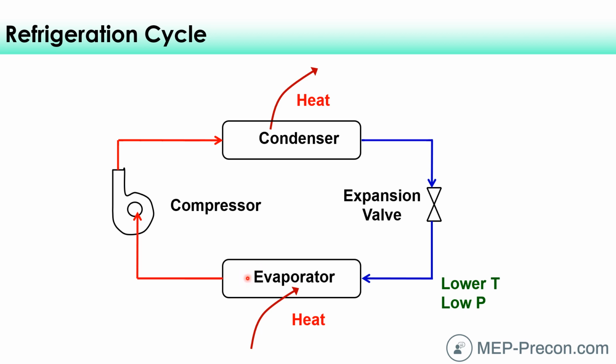to our compressor. Before it does, let's talk about the state of the refrigerant. As it has come in here, if I didn't mention that before, it's a liquid at a low temperature and low pressure. And as it absorbs heat, it evaporates, because that's kind of the name of this, the evaporator. That's the job that it does on the refrigerant. It evaporates the refrigerant. It's literally boiling off.